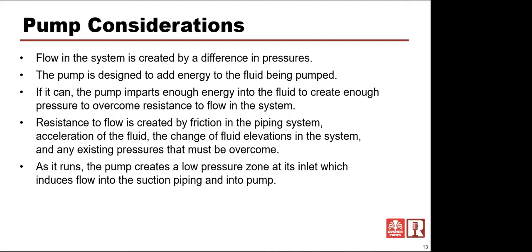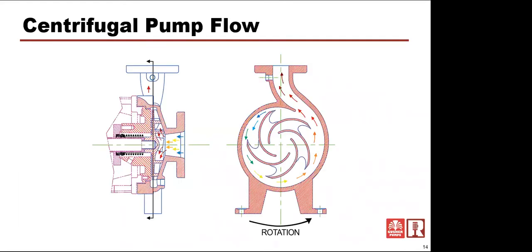As it runs, a pump creates a low pressure zone at its inlet, which induces flow into the suction piping and into the pump. If we look at a pump itself, you see suction coming in, picked up by these impellers. It's then circulated around the outside of this volute until it comes over to this area, which is the cut water that he was talking about in that video. And that basically separates the flow off to go out the discharge.